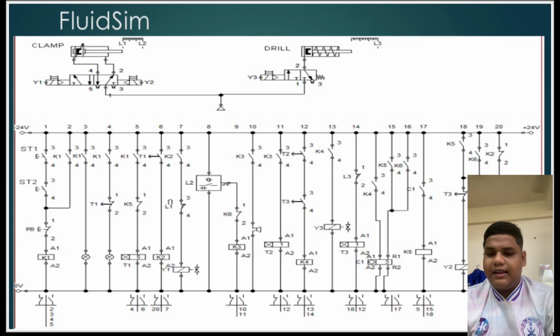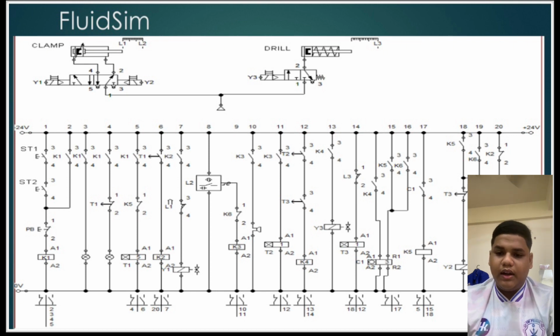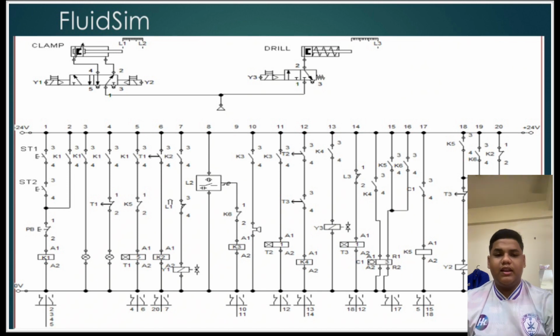On line 3, electricity through K1 continues to turn on the indicator light, and then on line 4, electric current through K1 continues to turn on the conveyor. Finally, on line 5, the electric current through the make switch K1 through K5 continues to turn on the relay with switch on delay, which means the time taken to extend the clamper is 5 seconds. When the clamper extends, the conveyor is off.